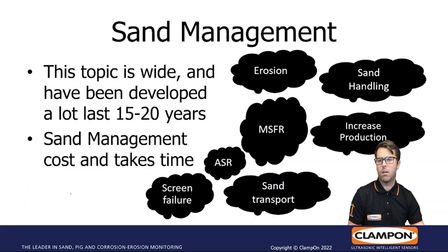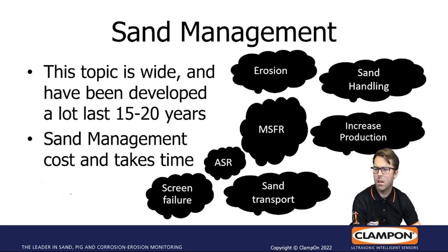When it comes to sand management, I already mentioned that this is different from company to company, and it's a wide topic, and it has changed a lot during the last 15 to 20 years. I remember 20 years ago, a very common comment was that, oh, the ASD doesn't work, I don't understand it, it's strange. But it has changed now so that actually they don't produce without having a signal from the ASD. So it's been a big change. Sand management takes time, but you get so much back for it.